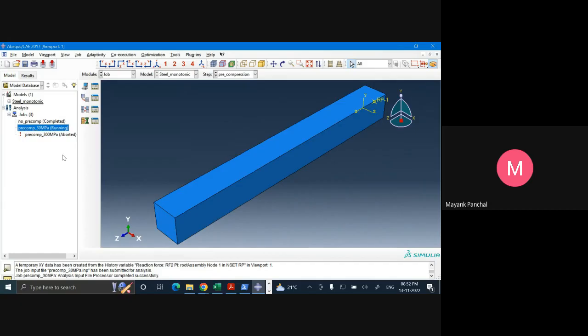How can you do it? You can do one thing. You can model a similar steel wall. Say you can write, if you want, the problem statement. You can model a steel wall. I'll send you the material properties. The dimensions of the wall should be: thickness 100 millimeter, length and width 1000 and 1000. So it's a 1000 by 1000 wall, thickness is 100 millimeter.